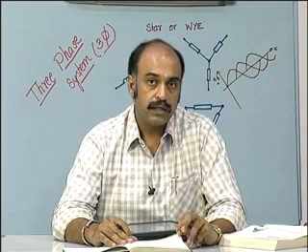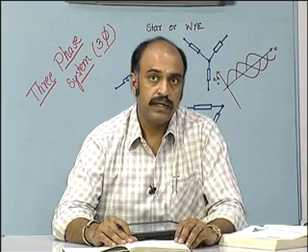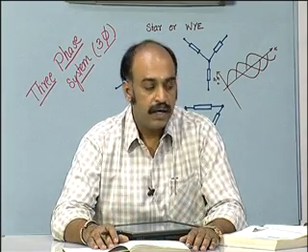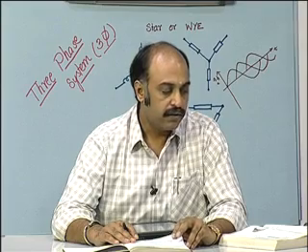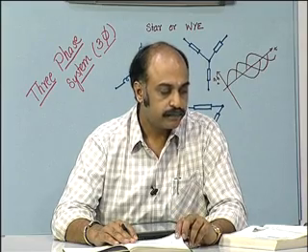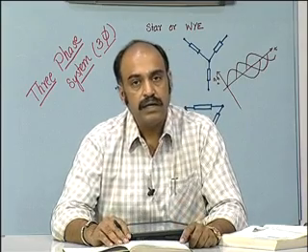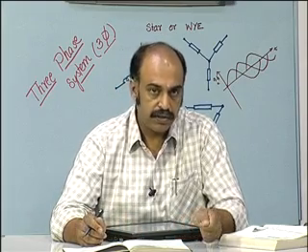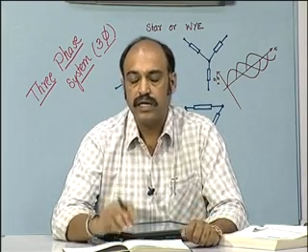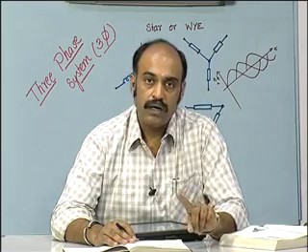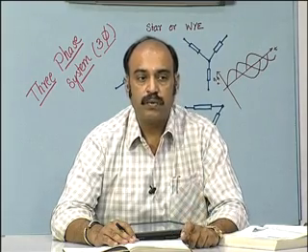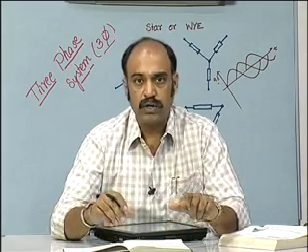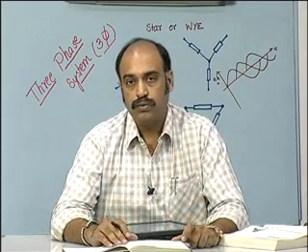In case the power factor is very low, less than 0.5, one of the watt meters can show a negative value. If it is a single direction watt meter, we must reverse the switch such that you could see the negative direction power flow, or you use a center zero watt meter, in which case you take the negative value, convert it into an absolute value, then add up the two powers.